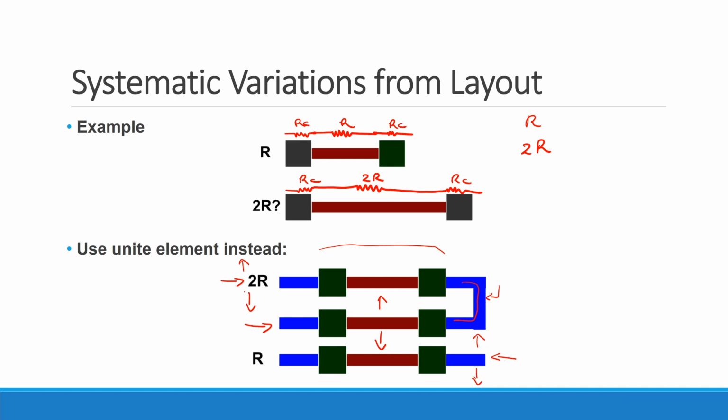Now, by the way, anybody know physically why this matters? The problem that I think is really the biggest one is probably more like a 5, 10, maybe even 50% kind of problem. Or why might it matter that the environment is not the same? Anybody know? How do you actually build this? What's the process you use? Well, okay, in general, what processes do you use to build ICs? So you use lithography to pattern something, and in particular for poly, you have to etch something away. Okay? Well, it turns out the speed at which you etch things away depends upon the local density of poly that happens to be there in the first place. Basically, if there's more material or less, you etch faster or slower.